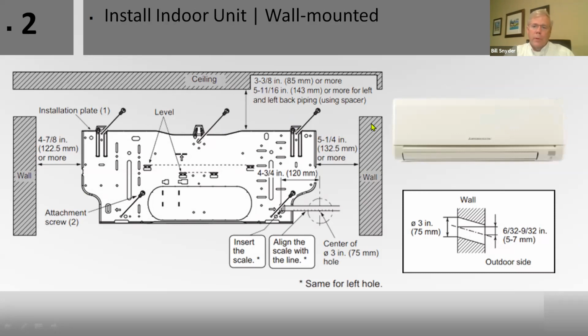When you clip this wall head over here, it's going to go on really tight. And then when this unit heats up and cools down, or the sun heats up and cools down the outside wall, you could get some ticking sounds as it expands and contracts on here.